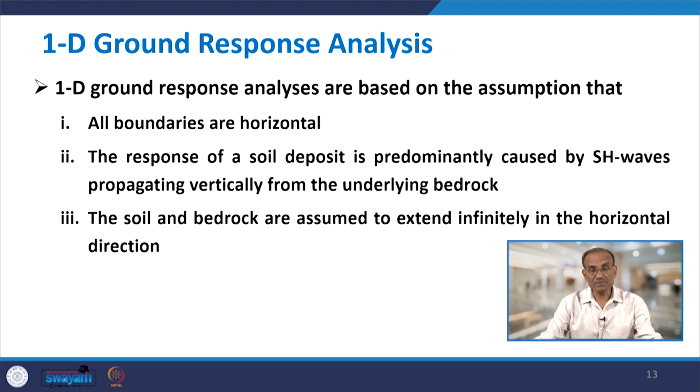Now, 1D ground response analyses are based on the assumptions that, number 1, all boundaries are horizontal. The response of a soil deposit is predominantly caused by what we call SH waves, which are propagating vertically from the underlying bedrock. So, first of all, they are SH waves.